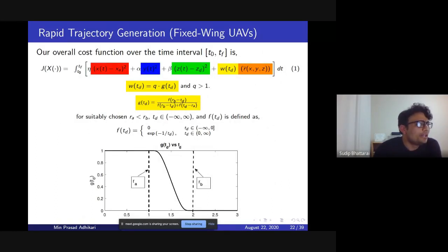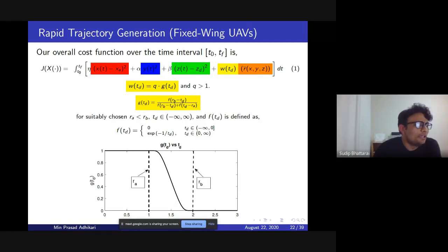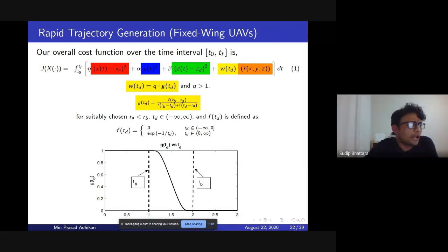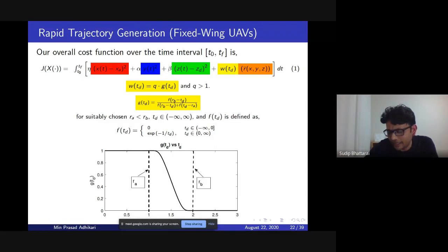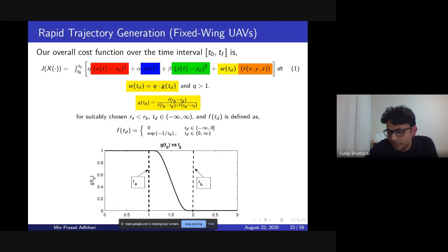So when you are estimating the value of G, the location RB, is that just straight ahead of where you're trying to fly in the line of sight, or can it be somewhere else? Is the gradient of how the terrain changes? Well, yeah, it could be anywhere. RA and RB is the location of obstacles, like nearby obstacles. It doesn't have to be in line, I mean, in the direction of flight or even in the reference path. It can be anywhere near the UAV, in any direction. Right. And it can be moving as well. Oh, yeah, of course, 100%. Right. Okay. And in page 35.